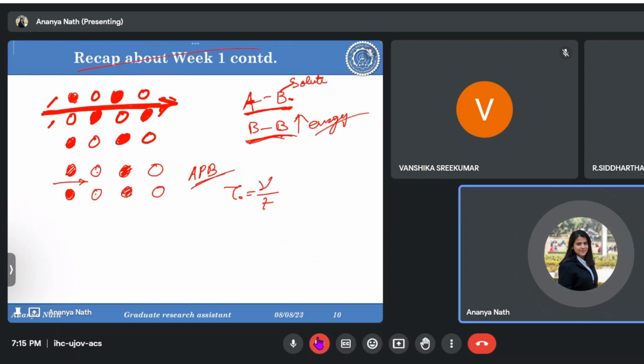So, solute atoms are always attracted towards the dislocation sites due to the interaction of their strain field, because as I said, there will be some strain field introduced inside the metal alloy due to the solute atom size or modulus or electrical or stacking faults. But the rate of the motion of these solute atoms will depend upon the diffusion rate. So diffusion is nothing but jumping of the solute atoms from one to the nearby vacant position.